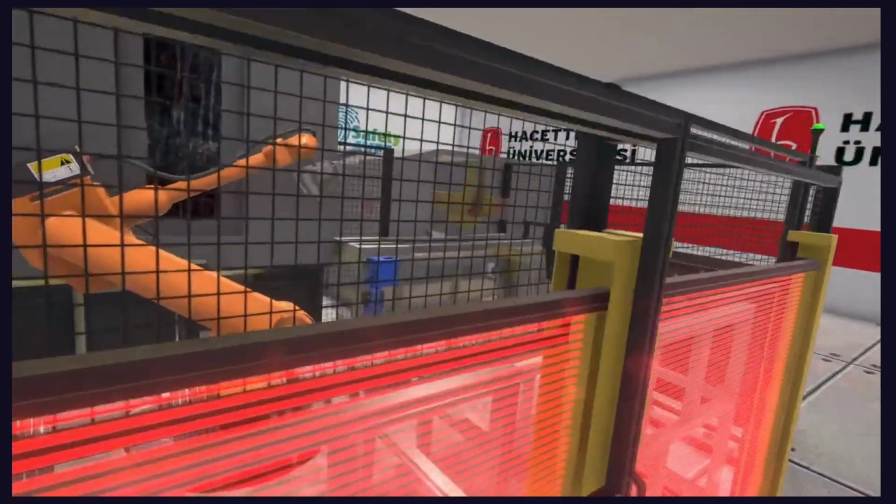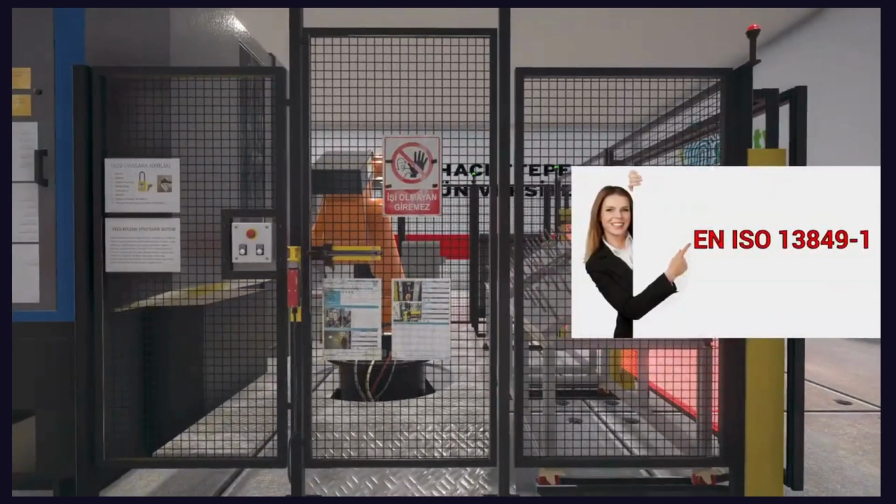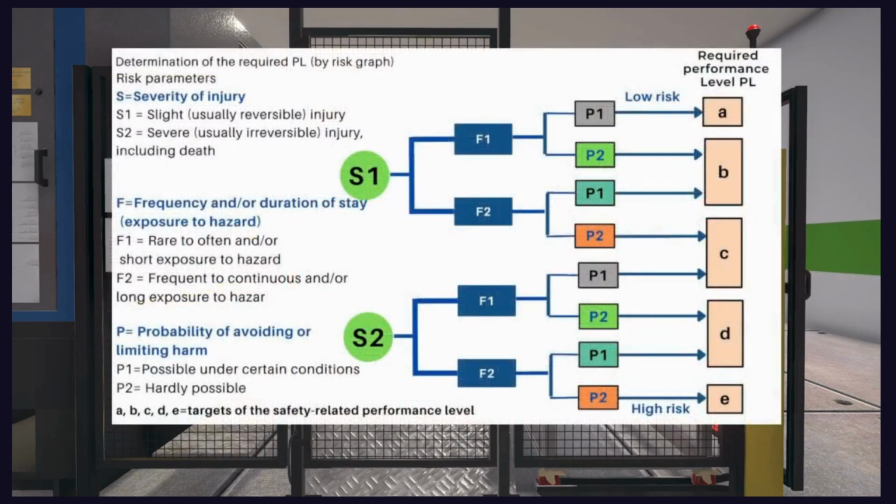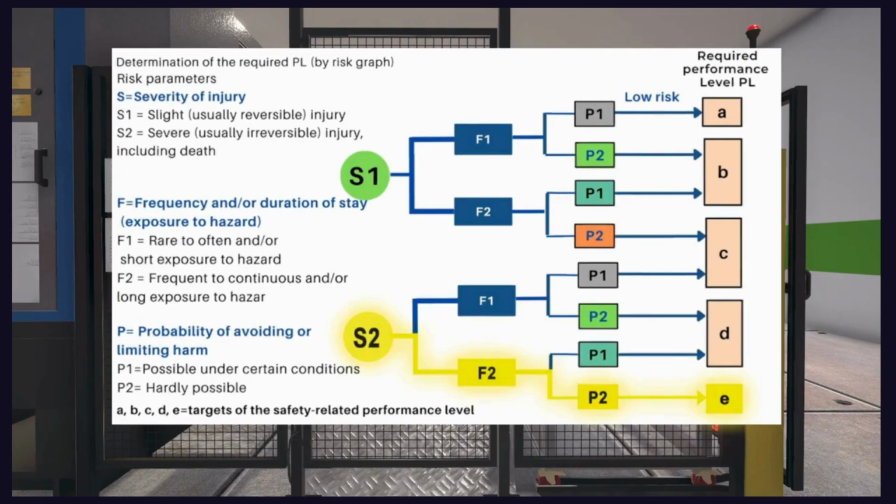Control system. According to the Machinery Safety Directive, it is necessary to ensure that a malfunction in the hardware or software of the control system does not lead to hazardous situations. All safety equipment on the machine should be included in the control system in accordance with the requirements of the safety-related components of the control system standard. The reliability of safety circuits is determined by performance levels, with PLe, performance level E, representing the highest level of reliability. According to the safety requirements standard for industrial robots, the performance level of the safety circuit for the light curtain should be at least Category 3 PLd, performance level D.